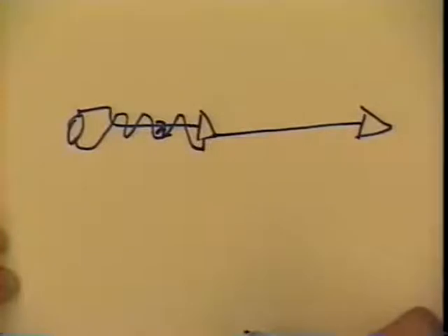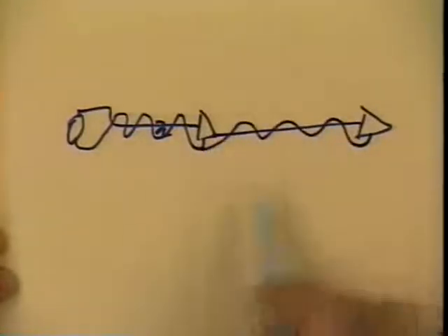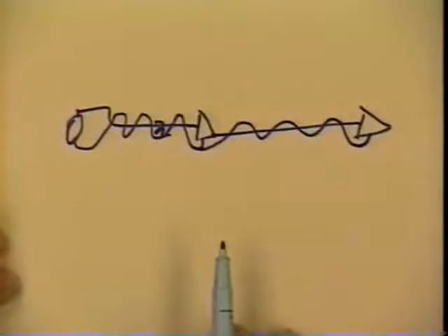Again, on a low inductance path. If they're traces on a PC board, they've got to be very close together, side by side. If it's wiring, I want to consider a twisted pair. This has nothing to do with grounding. This is all signal routing.